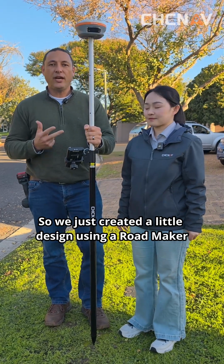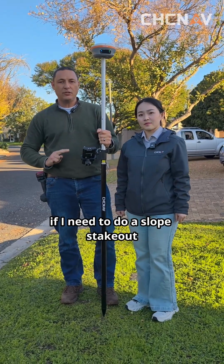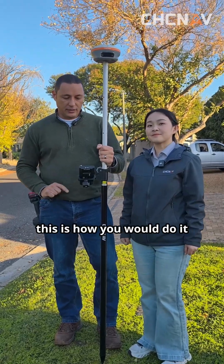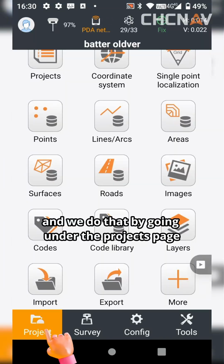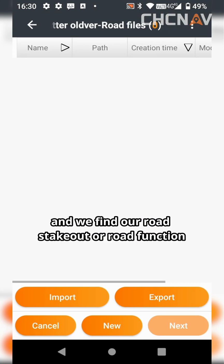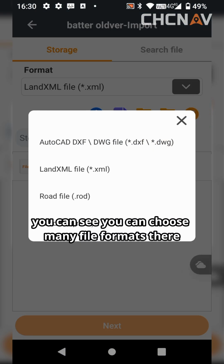So we just created a little design using RoadMaker, our software developed here in South Africa. If I need to do a slope stakeout or a batter board as we call it in South Africa, this is how you would do it. First of all, we will load a design file into LandStar, and we do that by going onto the projects page and we find our road stakeout or road function. And we will go import and we will choose, you can choose many file formats there.